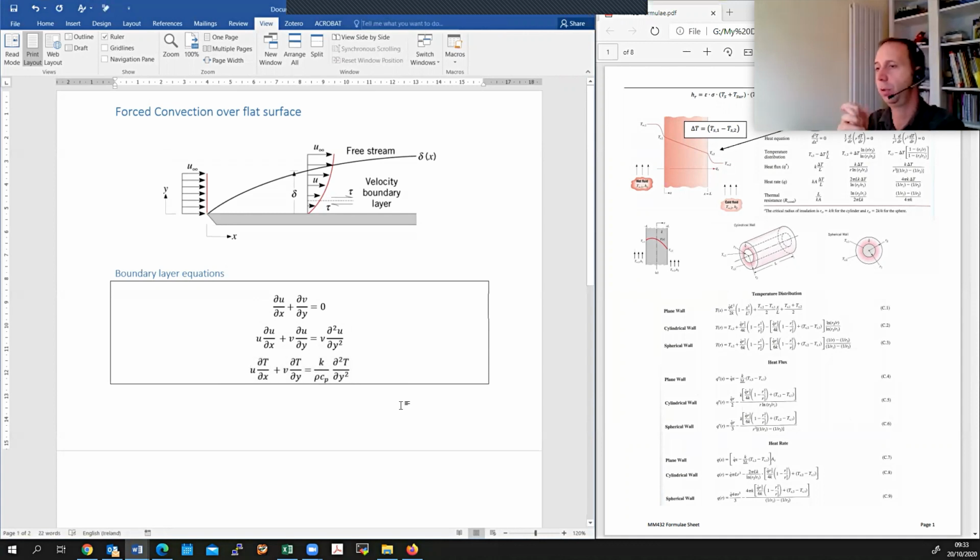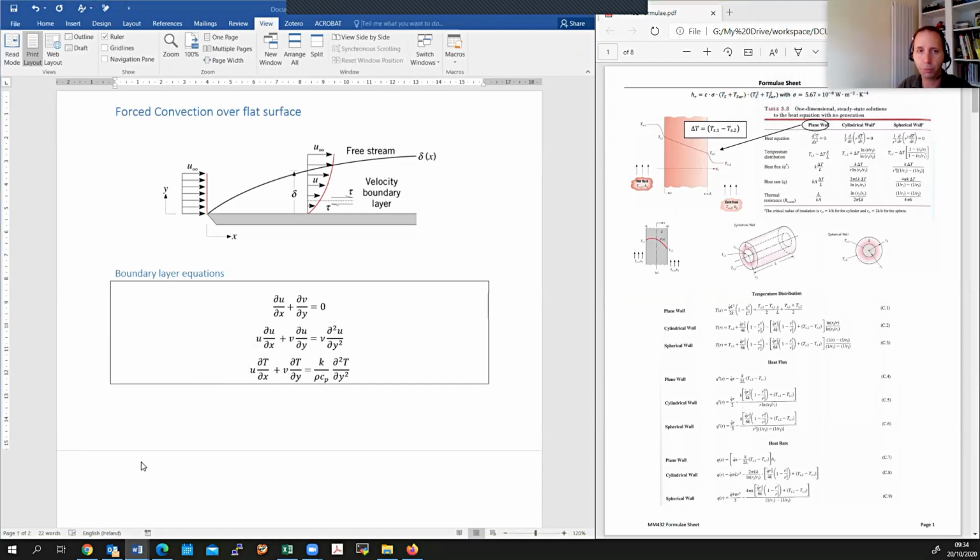Okay, so we're making progress. We know the governing equations for that particular flow, and we did some analytical assessment of the implication of that. And one of the things we came up with was a formula or functional description of the way the coefficient of friction depends on position and flow properties. Okay, so that's the equation we worked with, or that we ended up finding.